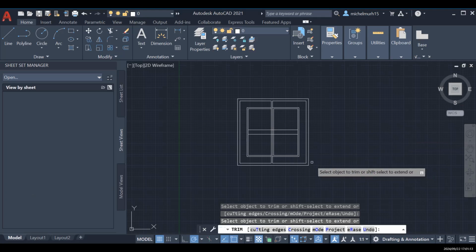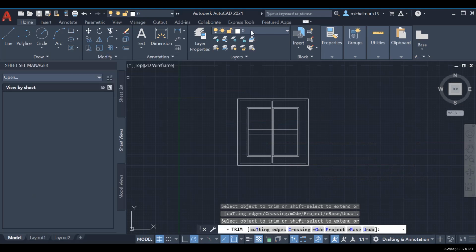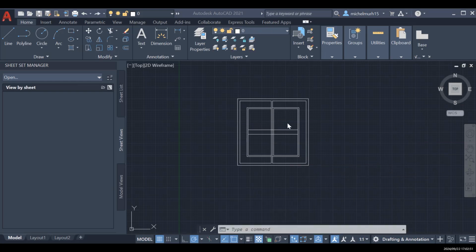All right. So the other thing that I'm gonna show here, let me do this first for you guys. From this junction here, I'm gonna show you how to fill the blank shape here. So I'm gonna use the hatch. If you go again on home here, under the home option, you're gonna see the hatch. Just click in here to have more options.